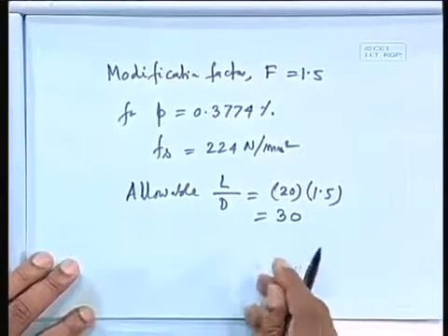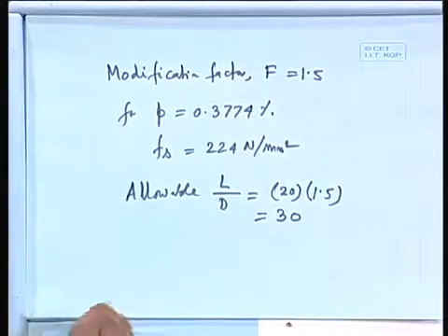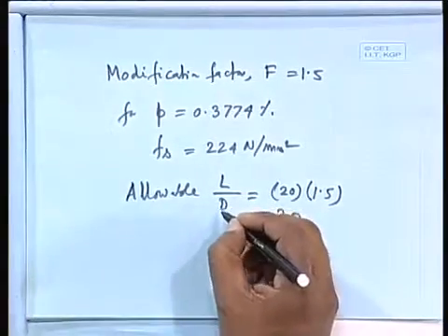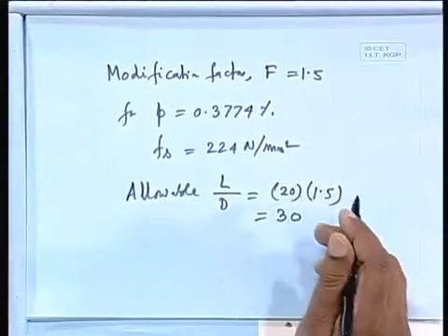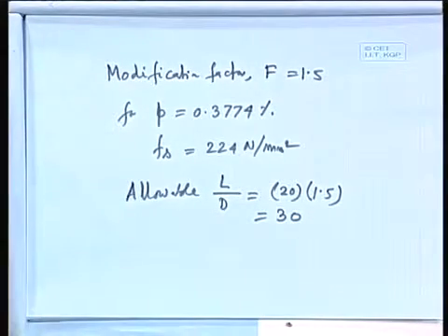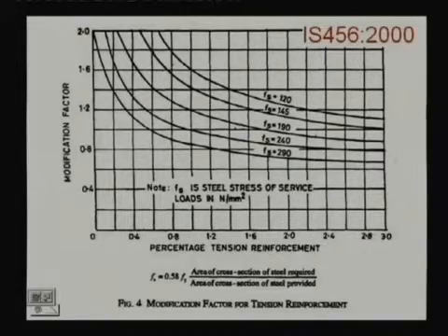There is a case here that you will find out there is one discrepancy. In one side it is written L by effective depth, that when we have told in the last one that is L, that span by effective depth, whereas in this note they have written it as span by overall depth. So this particular one we can take it as a span by effective depth also, because for beam and other things when we have used that basic values 20, in that clause they have mentioned it at your 20. So I can just read it. So that is in your clause 23.2.1.